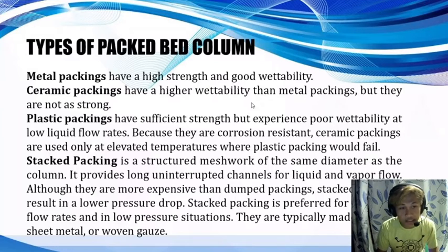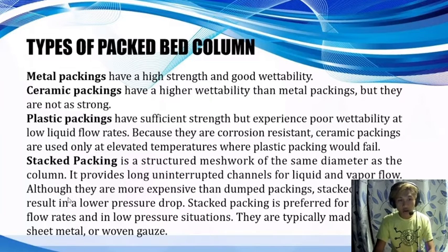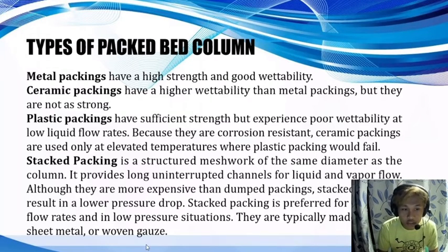The next one is the stack packing. Stack packing is a structured meshwork of the same diameter as the column. It provides long uninterrupted channels for liquid and vapor flow, although they are more expensive than dump packing. Stack packings result in a lower pressure drop. Stack packing is preferred for low liquid flow rates and in low pressure situations. They're typically made of wood, sheet metal, or woven cloth.